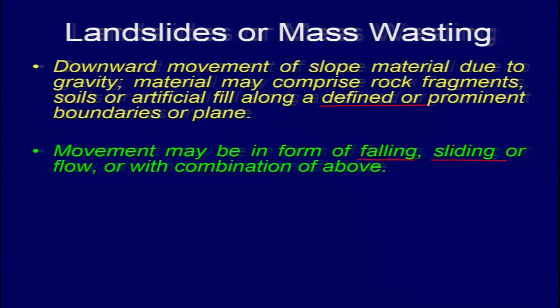Then we may have a fall, and we may have a slide, as I told, if you are having the bedding plane, or the material is fractured or jointed. And flow itself talks about very loose material, plus we can say that it is saturated.